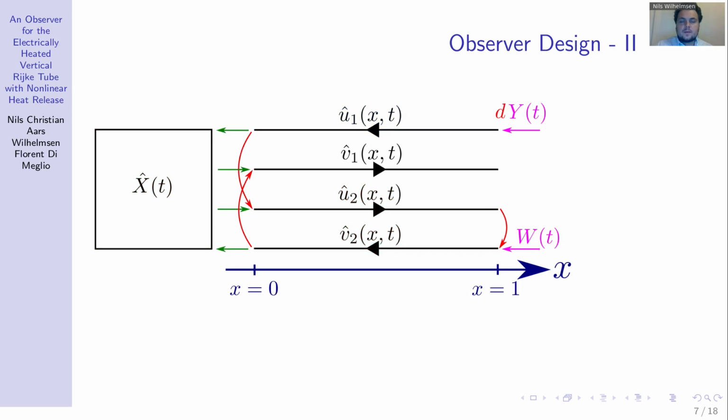Because of this possible instability, one has to go a bit further if global convergence is to be proven. Consider first the boundary circled here, which is the source of signals that become the measurement y after a time delay. Next, consider that this boundary also receives the ODE state as one of its constituent signals. The difference is that the signal becoming y contains this V2 signal. Using these observations, the observer is made by reconstructing this boundary circled in blue with the known signals. For details, consult the paper.